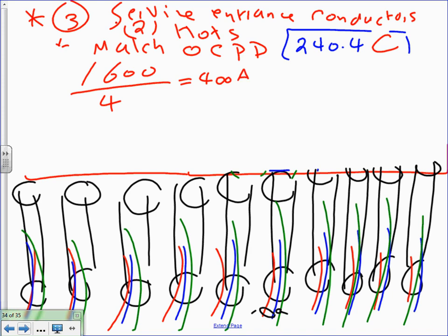The wiring methods. What did we do for wiring methods? Remember, we'll get screwed up with the wiring methods here. Are we using NM? You can't use NM-B as service, so it has to be any other system. How did we do it last time? You can't use NM-B cable for a service, that's for sure. Did I use it last time? I used THHW. This one is service, bringing the power to the building. You can't use NM, so that will be conductors.